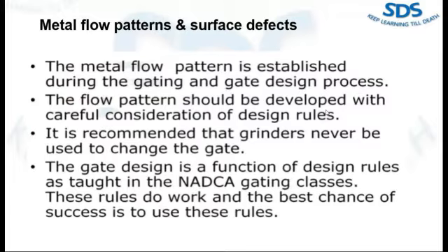When we are designing, we also do die design and manufacturing die design nowadays. So we follow the guidelines given by NADCA, and some things we also validate with the time of experience. The practice of using a grinder to modify the gate for a part should never be used. This process is not precise enough to ensure that the resulting gate complies with the design rules.